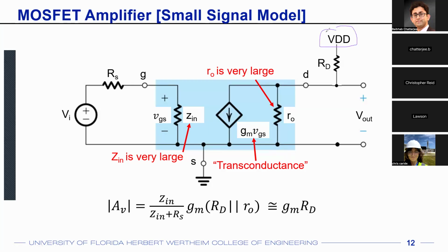So you have the VDD connected at the top terminal of the RD resistance. And VDD is a DC voltage, right? Now, something that I said in the first or second lecture, that any DC quantity is an AC ground, because the AC voltage on a DC is 0. If you talk about a 5-volt DC, it's a fixed 5-volt voltage. There is no AC component. So the AC component on the DC voltage is 0. So any DC voltage in terms of AC is a ground.